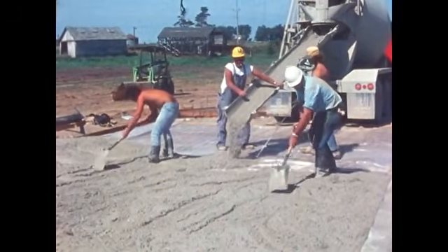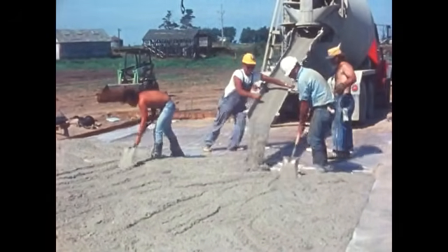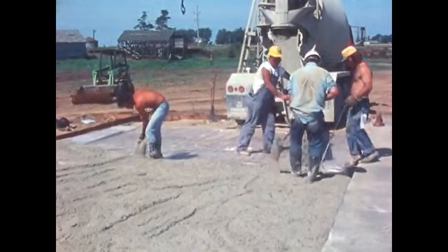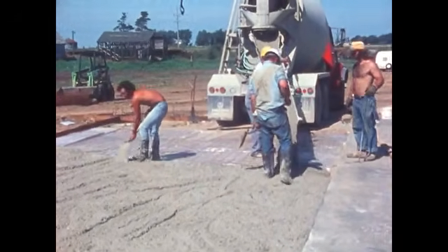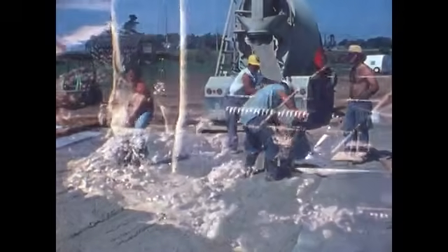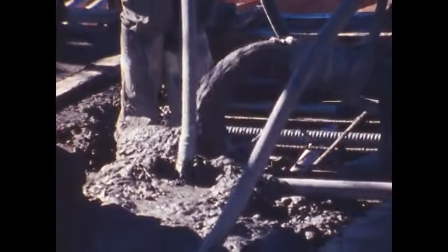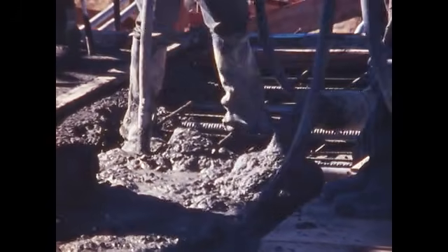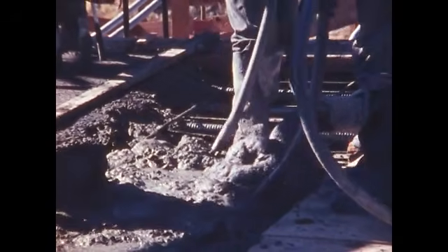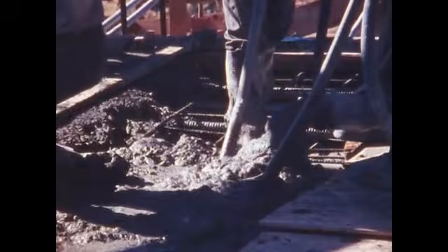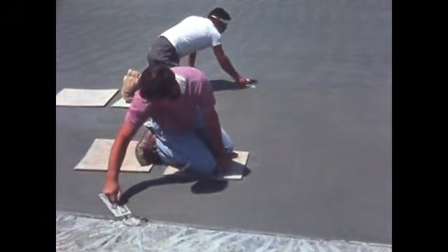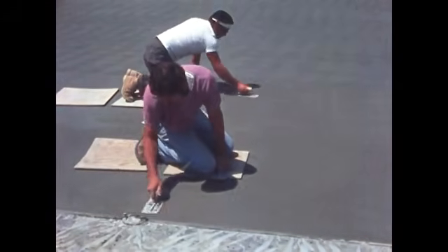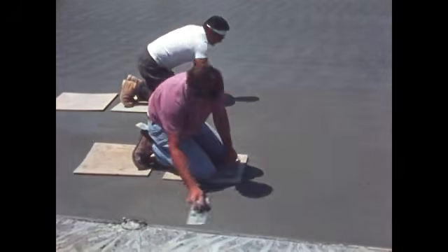Two additional factors, workability and finishability, should be considered when applying these principles to the design of a concrete mix. Workability is that property which determines the ease with which the concrete can be placed and consolidated without excessive segregation and bleeding. Finishability relates to the ease with which the surface of the concrete can be worked with finishing tools.